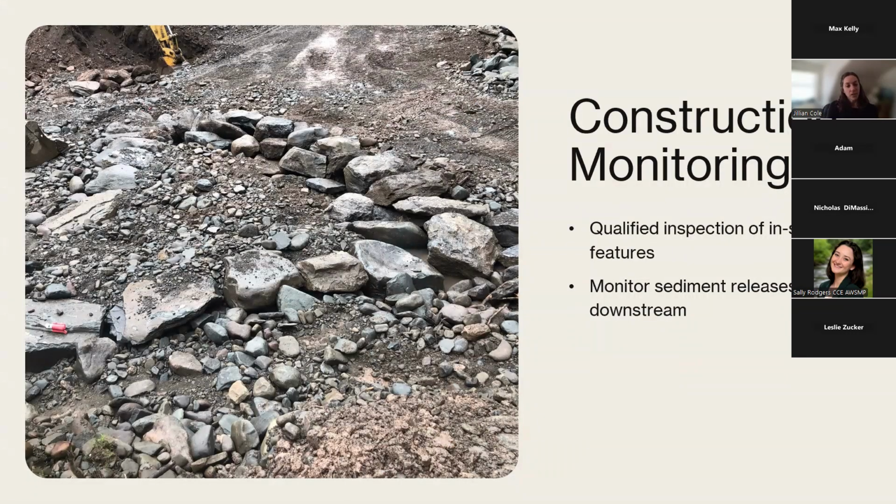And then finally, during construction of the in-stream features, a qualified inspector should be on site to observe installation. A lot of times contractors are not familiar with the proposed structures that are put in the stream, especially if they're a bridge contractor. And proper installation of these structures is definitely necessary for long-term stability and to ensure that they function as intended.